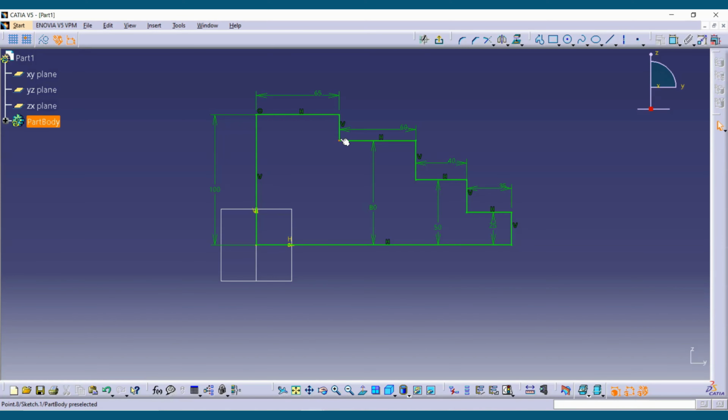Make sure that the profile doesn't have any intersecting sketches, such as lines between these two points. Sometimes we start drawing these lines from these points also. So make sure these lines are not coming in between, and the profile is completely empty in between. There is only one start point, the line will go above and then close the profile at the end only. In-between sketches are not required. If they have been made, it will cause an error in the shaft command.